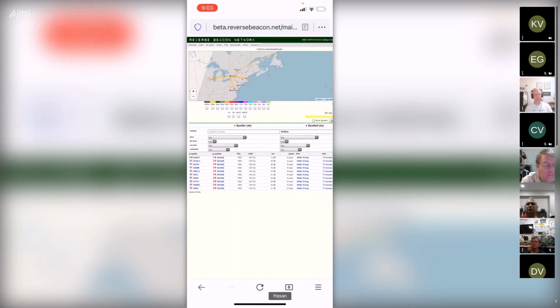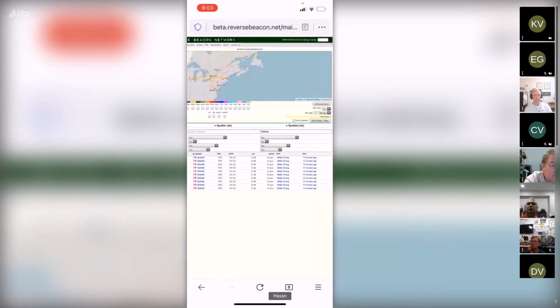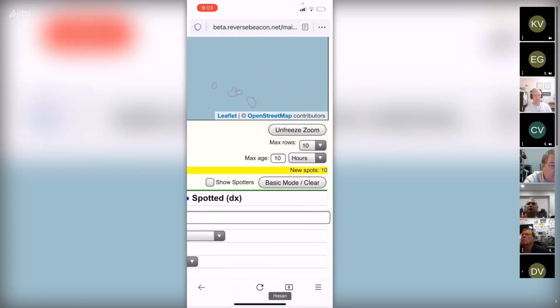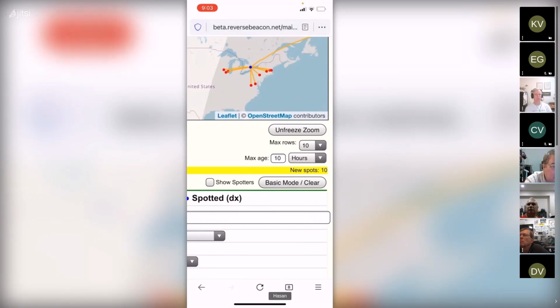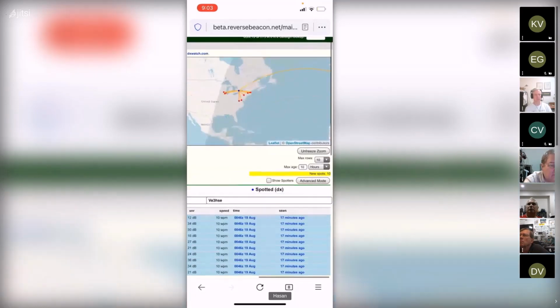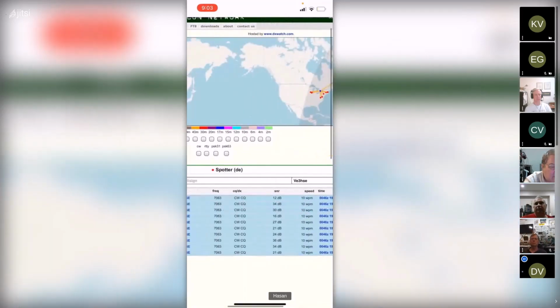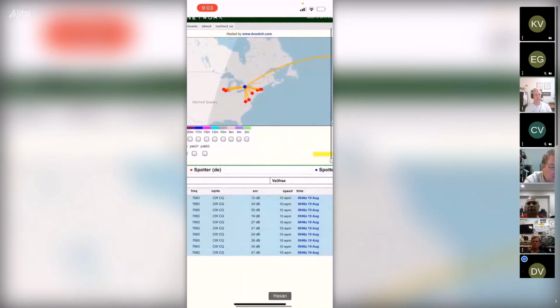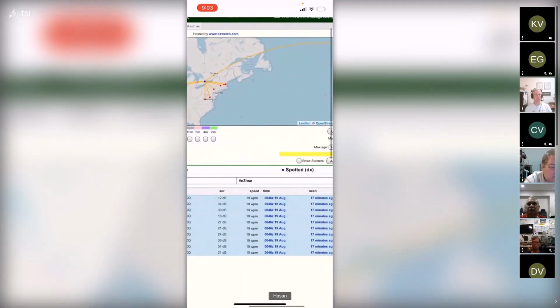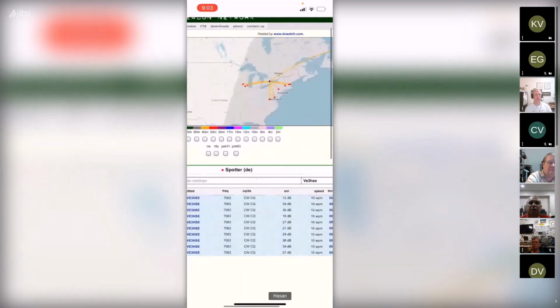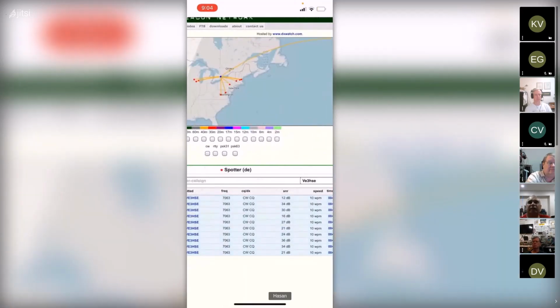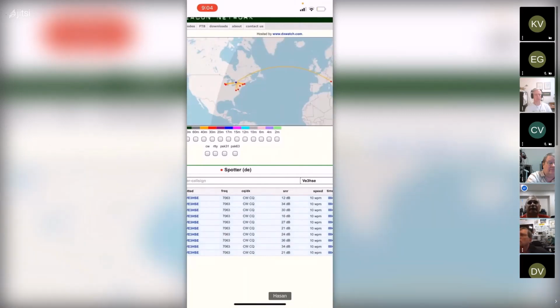So is this 20 meters? This is 20 meters. Oh, yeah, I'll show you guys the results from 10 hours. 20 meters. I think your takeoff angle is a lot different. I think that's the problem. I think on 20 meters, your takeoff angle is going to favor hitting the first skip zone. So you're on 40 meters. Wait, I'm sorry. I keep getting those two confused. This is 7 megahertz. This is 40 meters. Yeah, so that's 40 meters. This is NVIS, man.